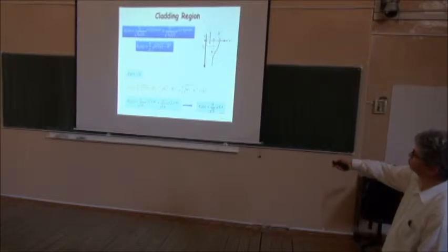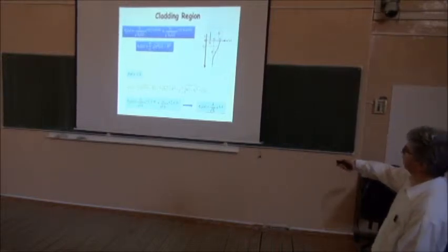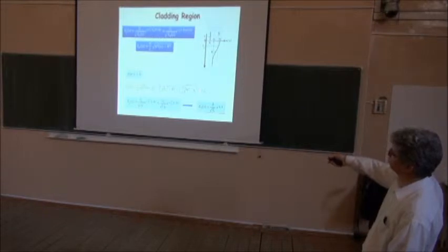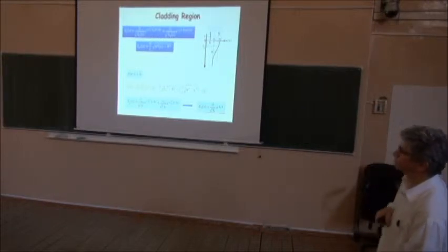But I know that this refractive index is smaller than my effective index, so I can factor a -1 out of this expression. I get this imaginary number j here, and I have the difference between two positive numbers, which we can define as a pure imaginary number gamma.